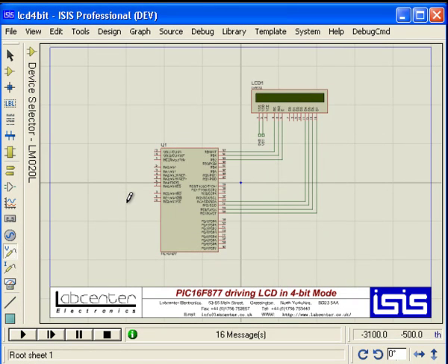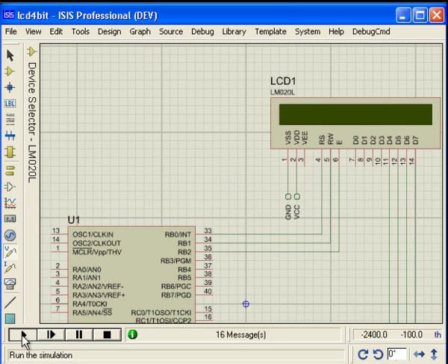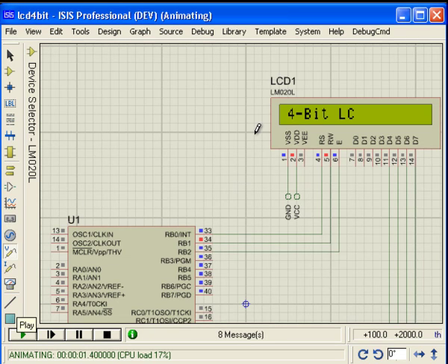This demo explains how to set breakpoints and single-step code using the inbuilt Proteus debugging system. We will use a simple 4-bit LCD driver sample with a PIC16 processor. If we start by running the simulation, we can see that the controller writes text characters to the LCD and then uses custom characters to delete them.